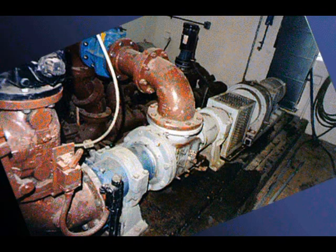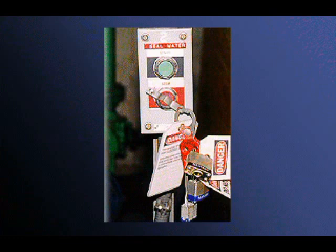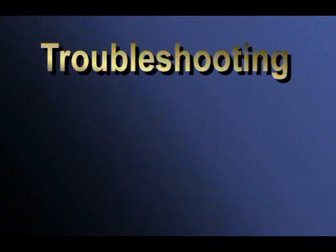Mechanical seals, bearings, couplings, motors, valves, and other components require regular maintenance. Be sure to refer to the earlier discussion in this course and to manufacturer's literature. As a source of information and reference, a troubleshooting guide for the progressing cavity pump follows this section. Remember to always lock out the pump before performing maintenance on it.